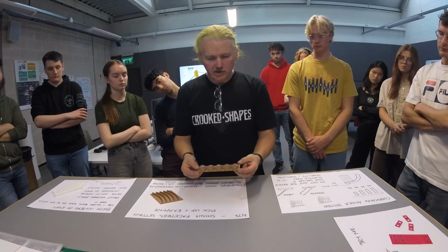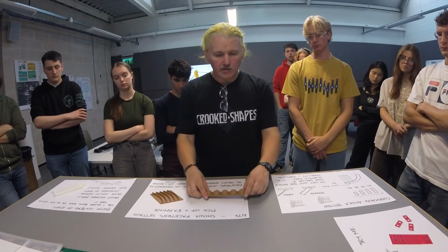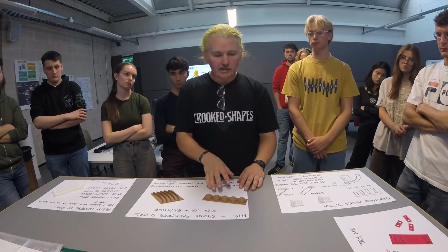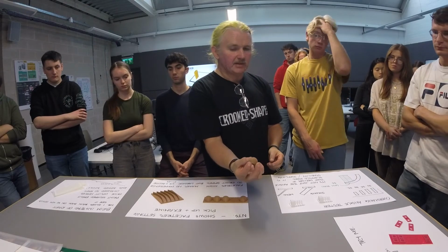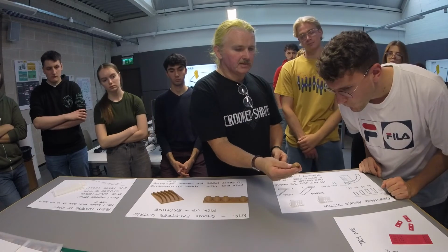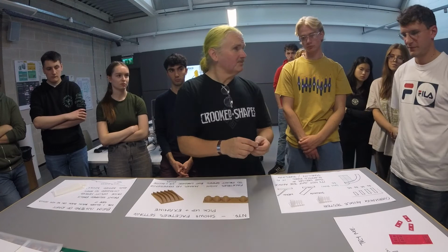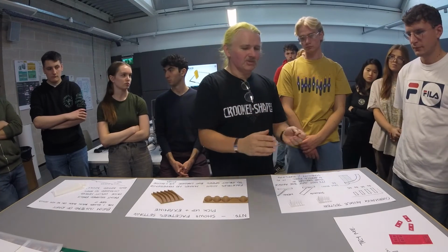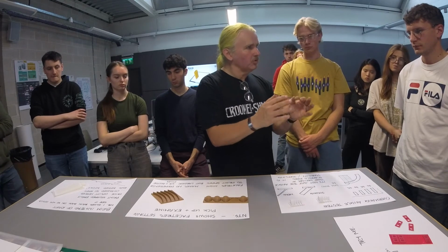So another consideration is the smoothness of the objects. If we did a sphere in AutoCAD and sent it out, just as I've done, using the STL out command without any changes, it's at that quality level, 0.5. So we can see the facets on it. They're not big facets, but it depends on the size of the object. If this was a bigger ball, it's not going to be huge because it won't fit on the printer, but if it was 5 or 6 times that, then they would be more noticeable.